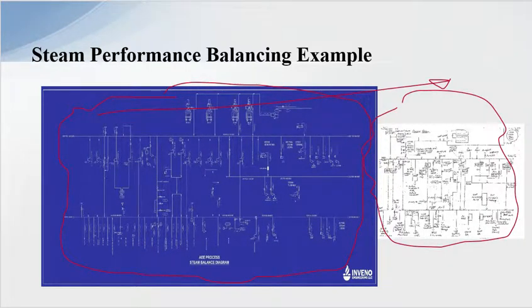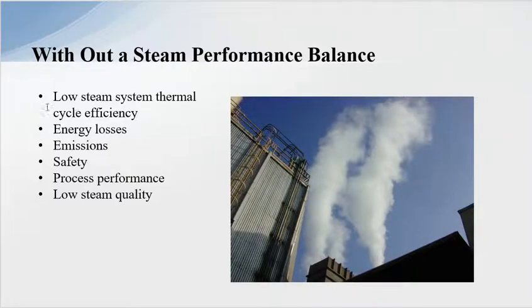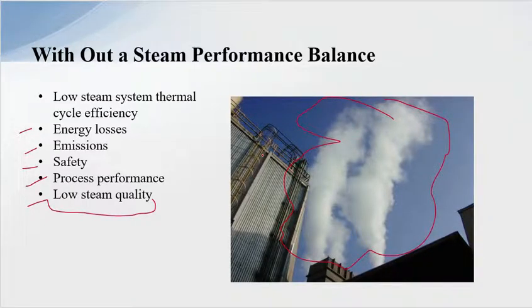So, without steam performance balancing, you get low steam thermal cycle efficiency in the plant operation, energy losses, emissions, safety issues. I find safety issues all the time because people do not have knowledge of the safety valve settings. Performance, the process, low steam quality is another one. And again, we're sitting there venting all the steam to atmosphere, heating up the ducts.